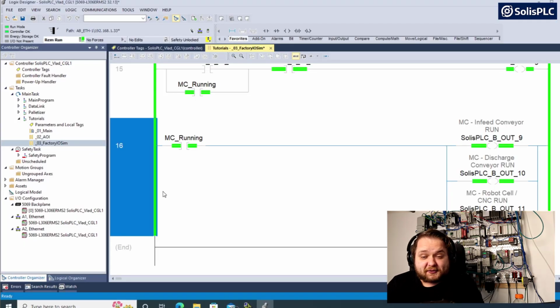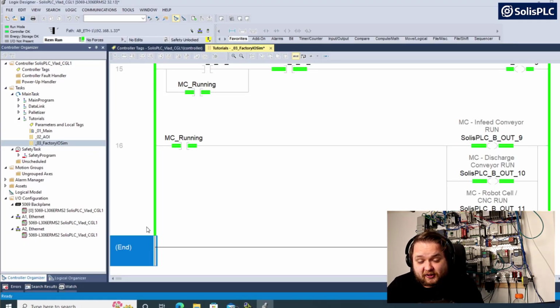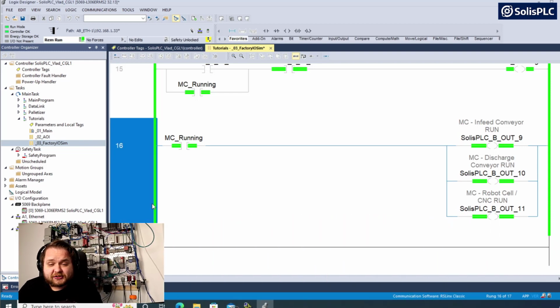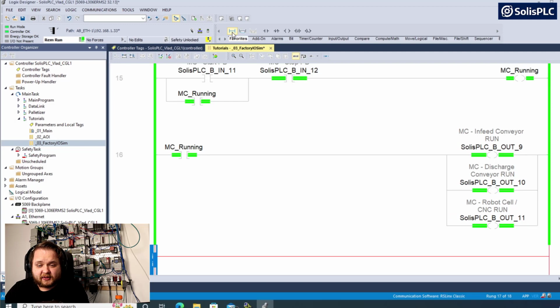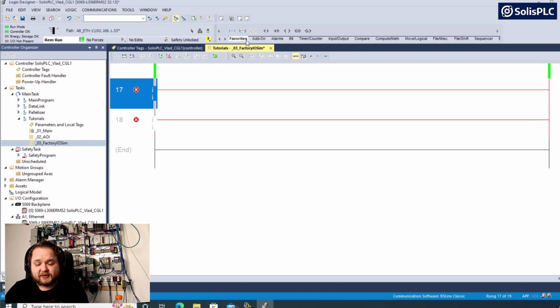So here's another little trap for automation professionals that are just getting started in controls, which is using the OTL and OTU instructions inside of your PLC. One of the most obvious ways that we could program this is we have two inputs and we're toggling one single output. So common sense dictates that I can create two rungs. On the first rung, if the toggle position is 0, I'm going to latch the lids. And if the toggle position is 1, I'm going to unlatch the lids.